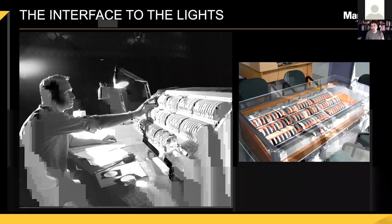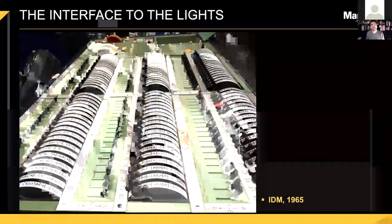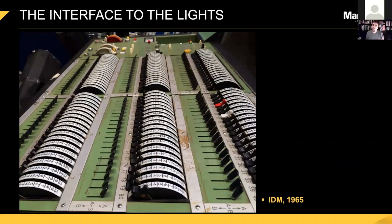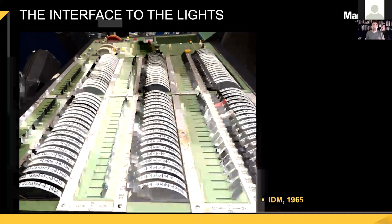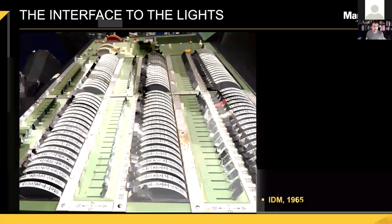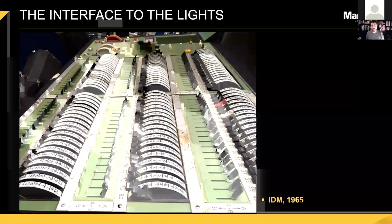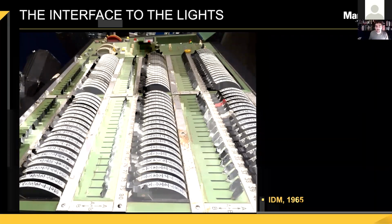And that was a challenge when computers came along, because the people who made early computer controls felt sort of honor bound or marketing bound or something to provide that same interface. You weren't going to be considered a real lighting console unless you had 120 faders for a 120 fader system. So this is IDM, Instant Dimmer Memory, which is also called MegaKey, I think, in America, from about 1965. So it's a single preset, but you still have 1 fader per dimmer. So you could still set states exactly like you always had before you then stored them.